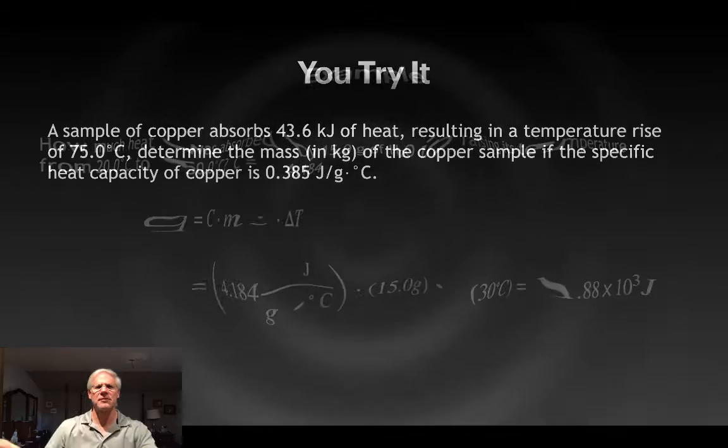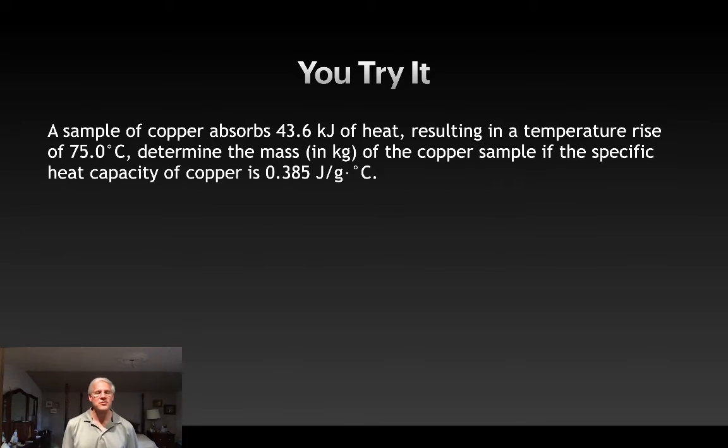Hopefully that makes sense. So here's an example for you to try using copper. We see that this copper absorbed 43.6 kilojoules of heat. You really want to keep in mind that that's kilojoules of heat. And the temperature rose in the copper by 75 degrees Celsius. Here you need to determine the mass of the copper in kilograms, and we're given the specific heat capacity